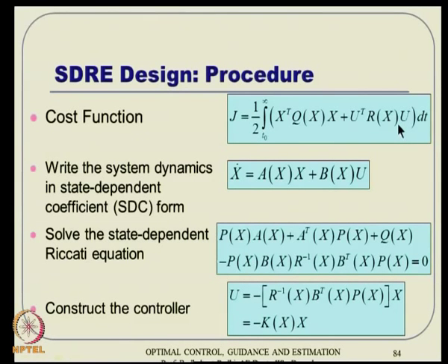So, the idea here is that we can treat, for a moment, that at any particular grid point it is actually a quadratic regulator problem, and hence we go back to the LQR theory and solve this Riccati equation at every grid point online, and then whatever positive definite P matrix comes out of that, I can use it in this formulation and compute a gain K. But remember, K is now a function of x, because at every grid point it has to take a different value. So, we essentially come up with a nonlinear controller, but with a linear looking structure.